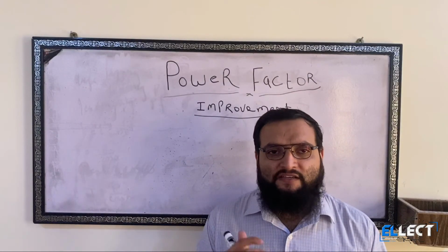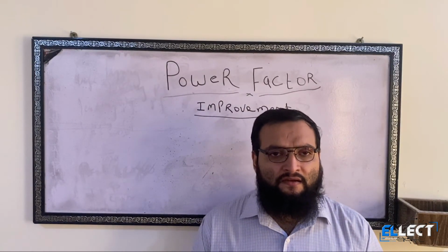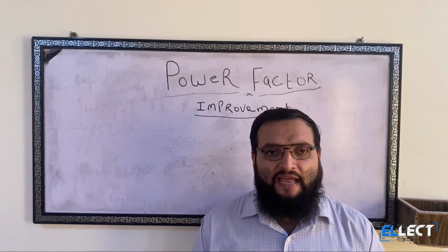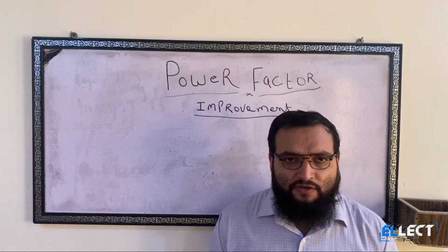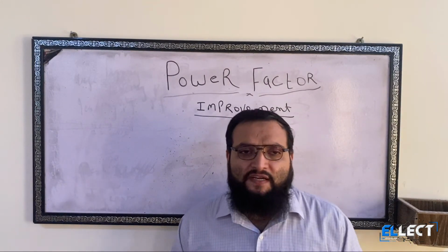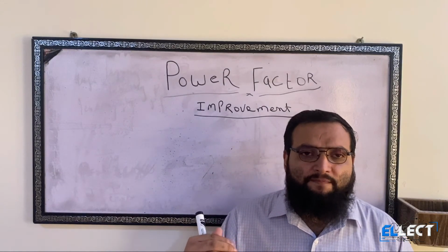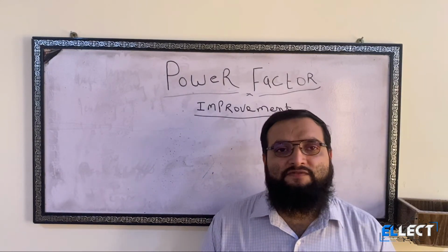Whenever we connect the exciters to the supply, we can increase the ampere turns of the induction motor, and that exciter will be supplied at the slip frequency.